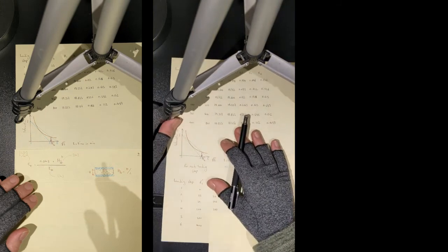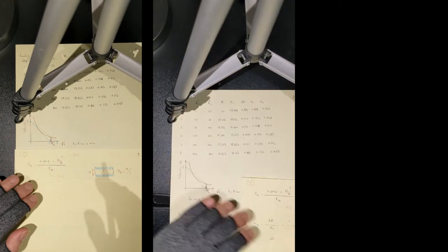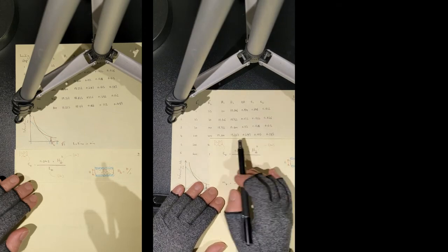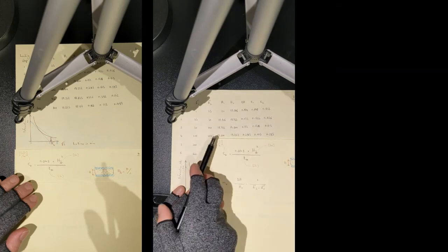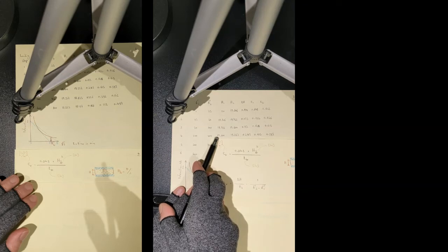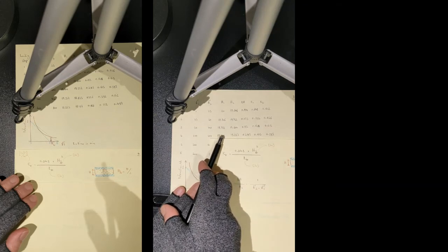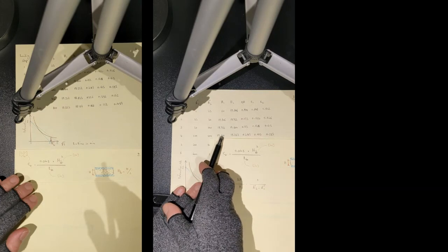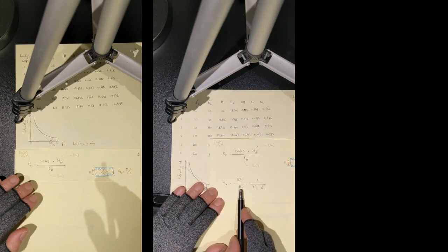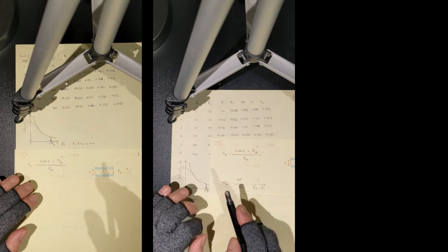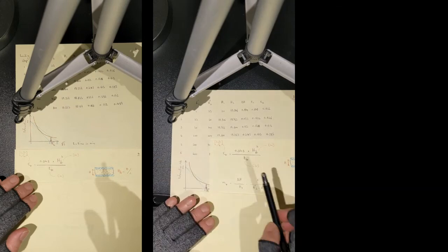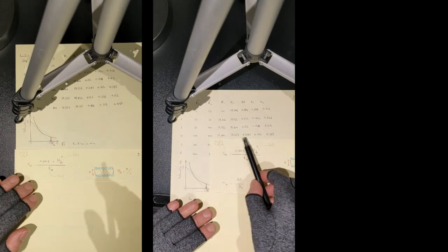Stage 4, so let's look into stage 4. This is stage 4. There we go. H1 is here, 19.60. So at the beginning of the loading step, the height of the test specimen was 19.6. That's H1. And delta H, how much the dial gauge showed you in terms of displacement at the end of that loading stage. Loading stage is 4, delta H 0.243.